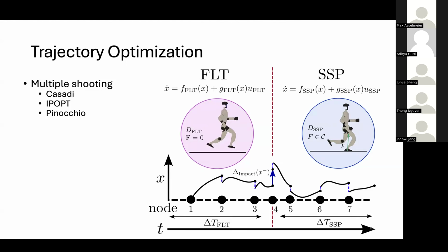If you optimize over the graph-based structure, you would generally end up with a mixed integer program. And a mixed integer program is pretty nasty to solve and not really something we wanted to deal with. Especially given that we're looking in the context right now of humanoid locomotion, the ordering of the sequences is generally known ahead of time. So in the case of running, we have flight phase into single support, back into flight. You know, this is a periodic orbit in the state space.